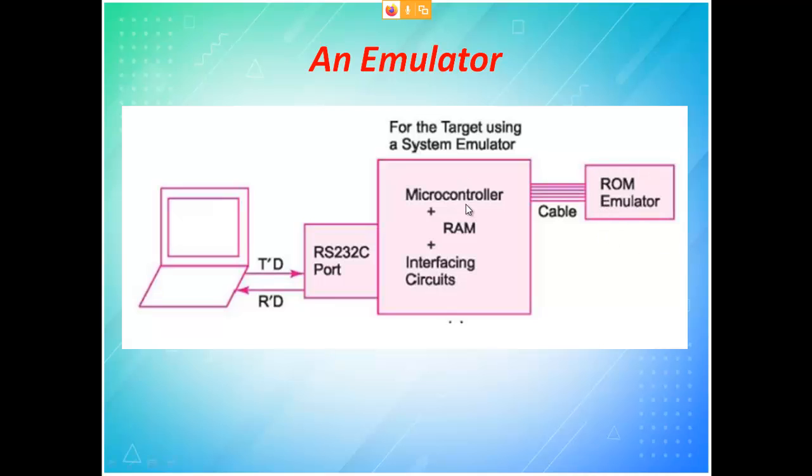That will try to generate as if there is some fault in the line, as if lightning occurred in that line, but actually there won't be anything. It is only generated by the emulator. Then we will see how your insulators are behaving, how arcing is taking place, all such things. That is called an emulator, and finally it comes to your program, and the program has to respond and give the answer. The program has to open the circuit breaker, open the SF6. That is written in the program, no? So that program will be verified. This is for the power sector.